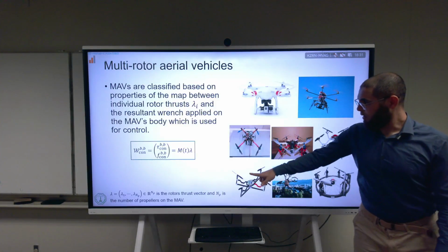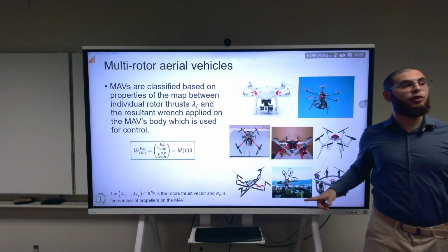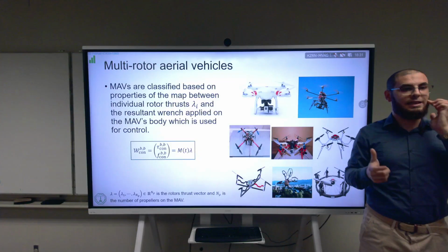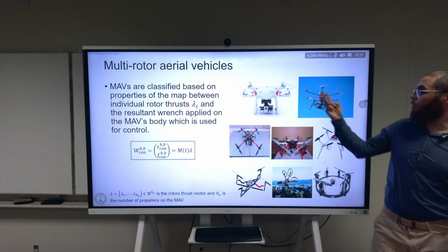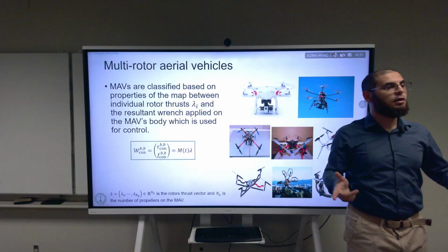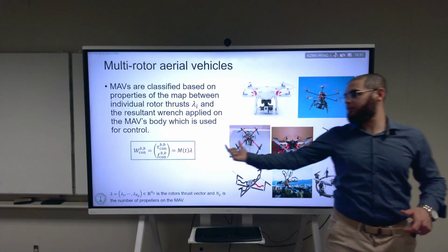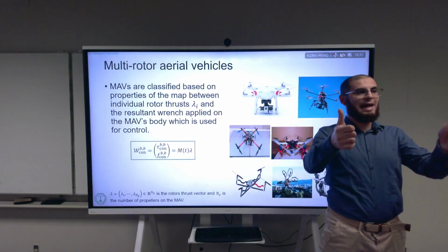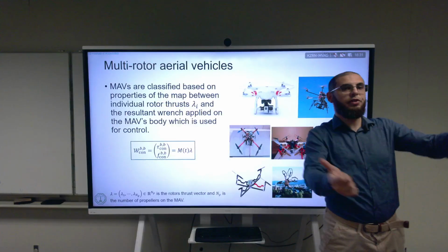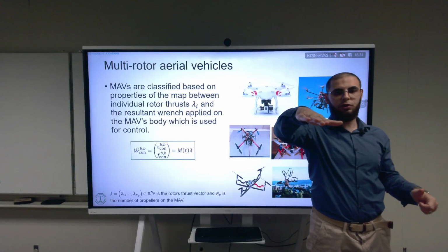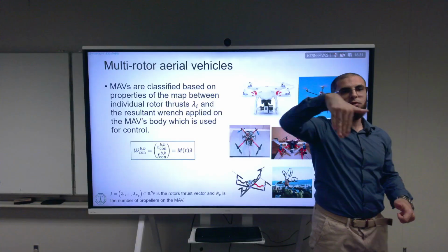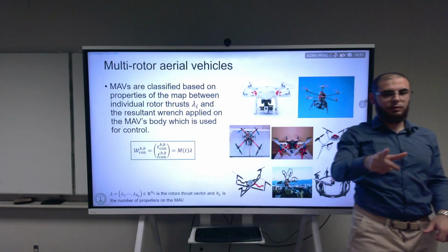All of these are fully actuated, but also overactuated, because they have more degrees of freedom than the 6, from the tilting. And the one at the top, the normal quadrotor and the normal hexarotor, are only underactuated. You can find it from the control allocation matrix, and it simply means that to move in one degree of freedom, it has to use another degree of freedom. For example, a quadrotor, to move left or right, has to roll, and to move forward and backward, has to pitch.